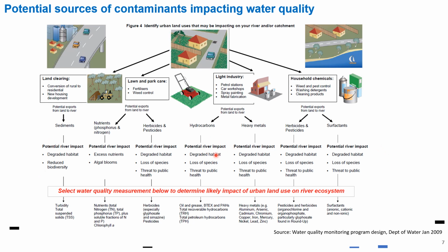Not only for rivers: if they are discharged to the ocean, it will also have an impact, even from a desalination plant. If you have a desalination plant in your urban setting and you discharge your brine directly to the ocean, it will change the water quality of that specific place where you are discharging the brine, because brine is concentrated, with a very high concentration of salts. If you discharge it into a specific area of your ocean, the salt concentration of that area will increase so much.